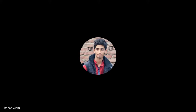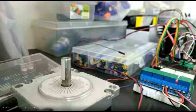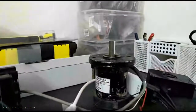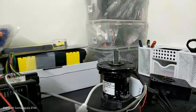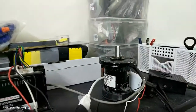Yes, sir. The tape on the front has moved to the side. If you look at the side now, you will see the tape over there. What's happening with the BLDC motor is that it is rotating, and you can see from the tape how many cycles it's going. It's rotating at 70 RPM. It's 70 duty cycle, 70% duty cycle.